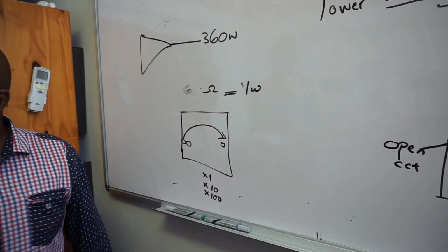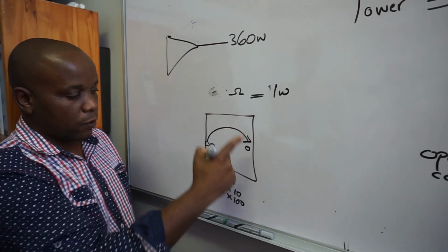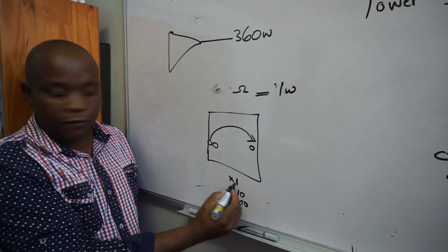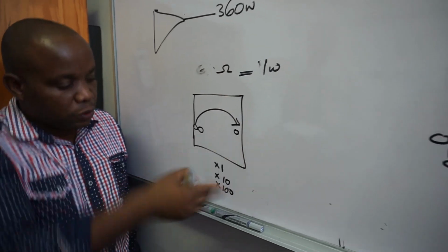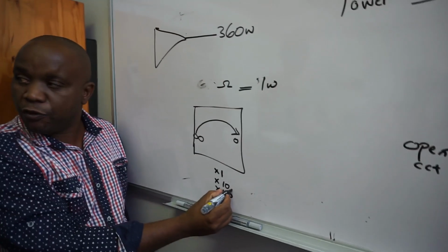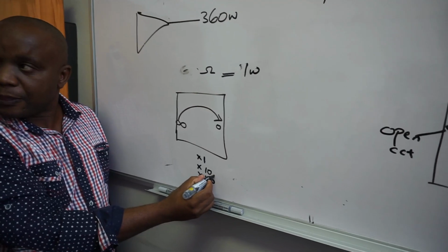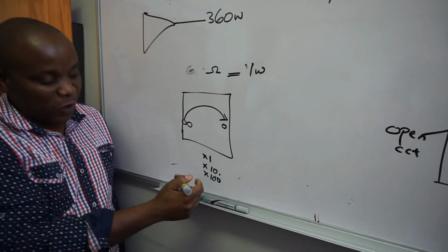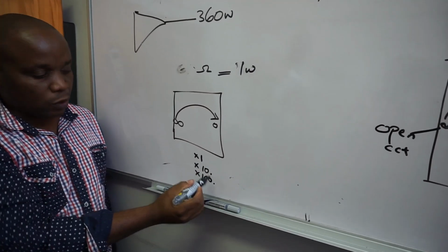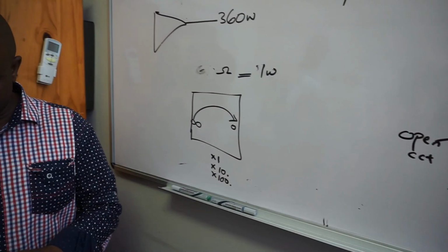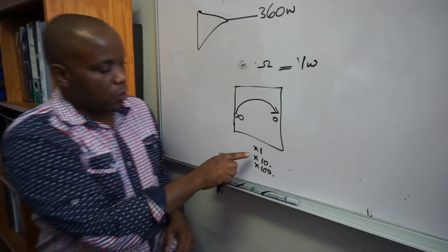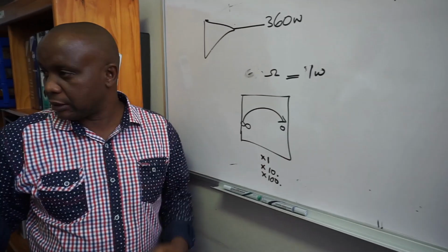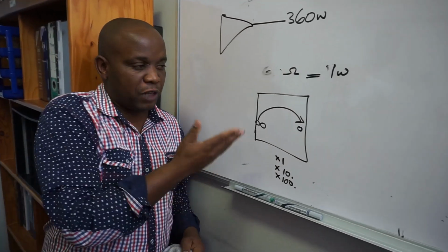Sometimes it might move to 0 because you're on the wrong scale. You've got a lot of speaker lines, but you are on a times 1 scale. So you might need to change it to a times 10. It will give you a true reading. Or you can move to a times 100. So the scaling means, you know, your installer has installed 10 speaker lines and is on a times 1 scale. So 10 speakers times 6 watt tappings will give you roughly about 60 watts.